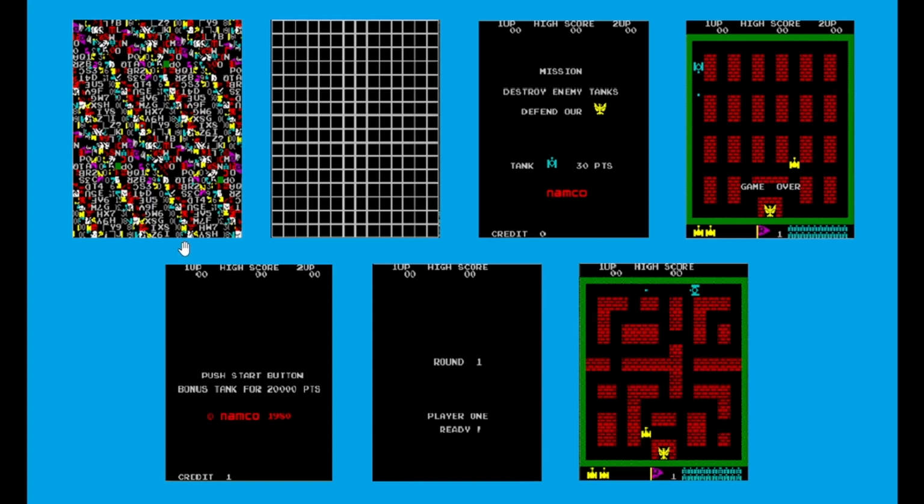During this time, it's not just a nice picture that gets plotted across the screen with these old arcade games. The program is placing a specific pattern through the entire memory map, including the video RAM, and that's why we see the patterns. It then reads back the results of the stored memory to see if it matches. If it doesn't, there's a good likelihood that a memory chip is bad, and therefore it can tell you which one to change. The second state is the test pattern grid.